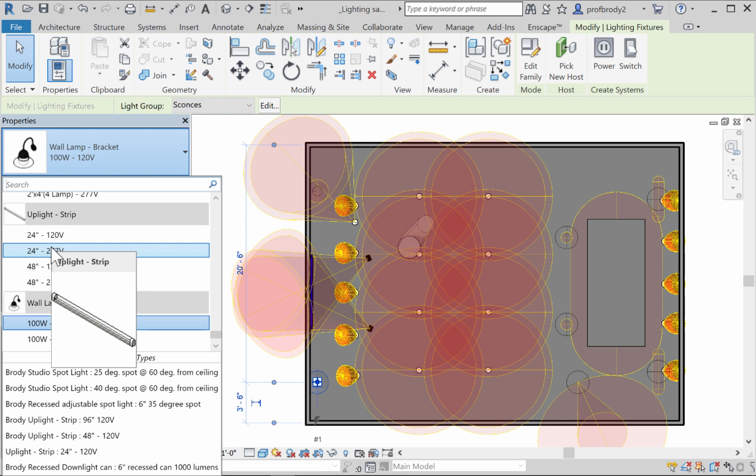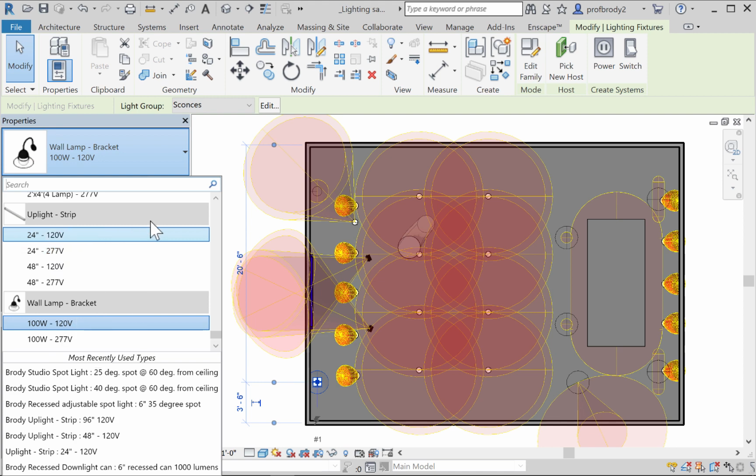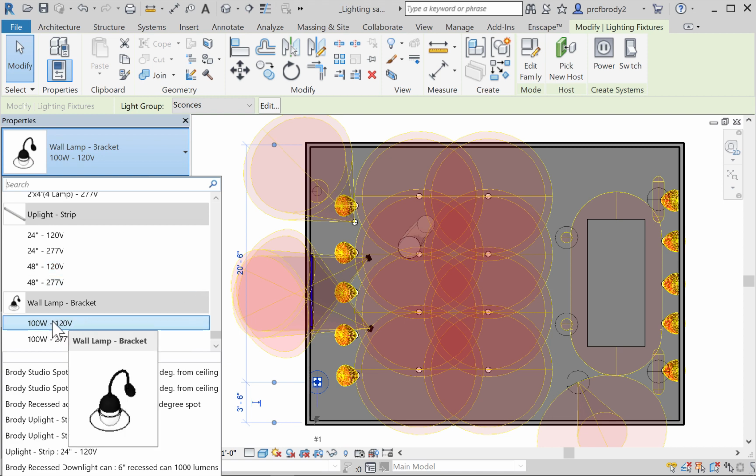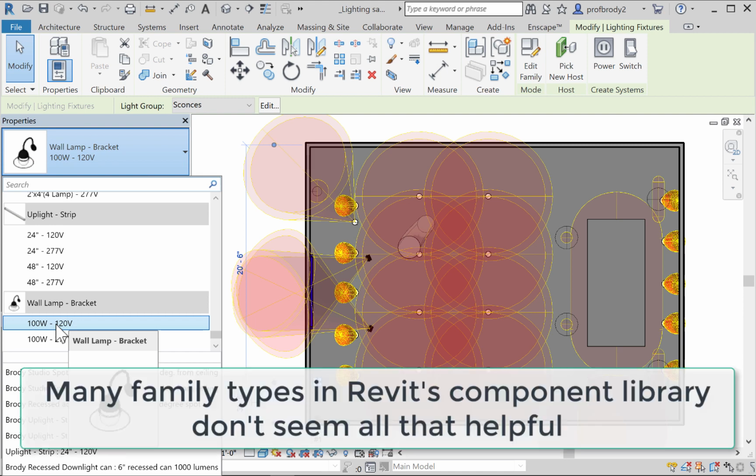The reason for this is these are common when you're doing kind of construction drawings. You're going to want to differentiate different types of lights. Often buildings are wired at a higher wattage, higher voltage, and so for the most part, you kind of ignore them. I would say as a rule, just have everything be 120 volts if there's an option.